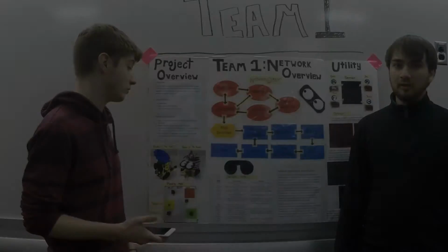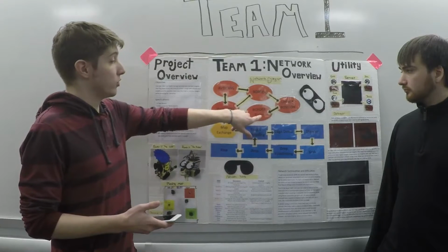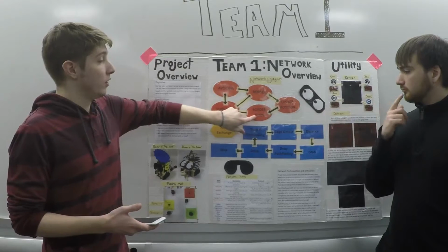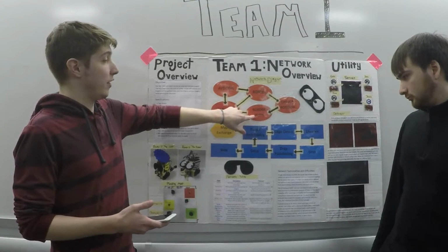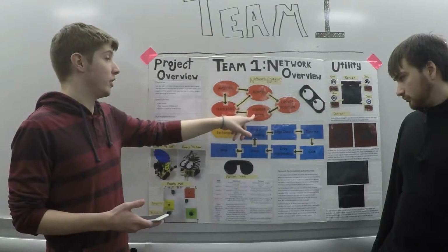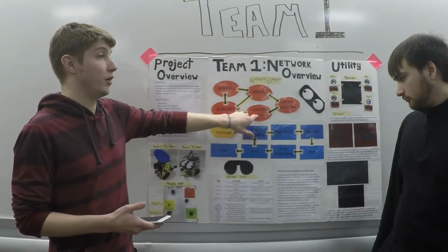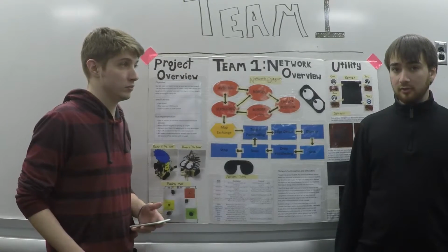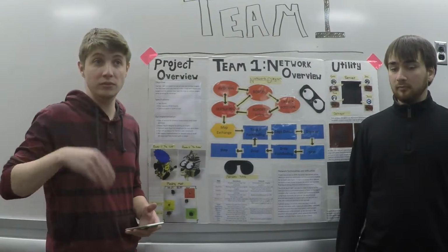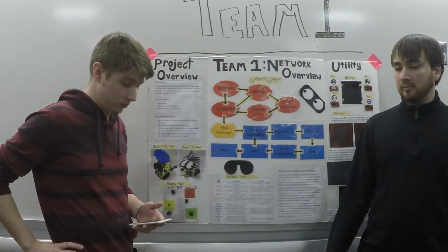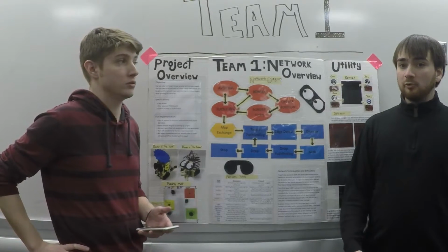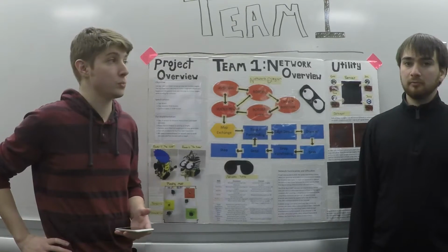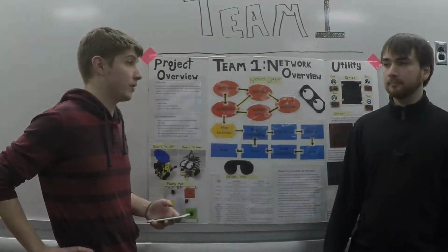So the next state is the border turn state, which occurs after we have updated our position. This state is a greater than 90-degree turn away from the border that then moves into straight line movement. And during this state, the only message that goes across the network is the movement message, which is the same movement message from before. It allows the rover to continuously update the angle as it is turning, just as it would when it encounters an object.